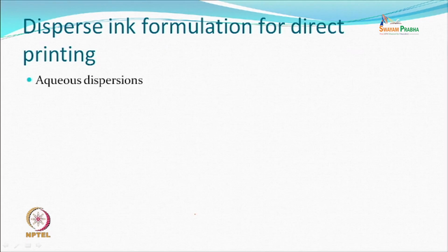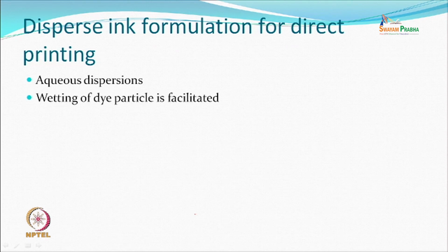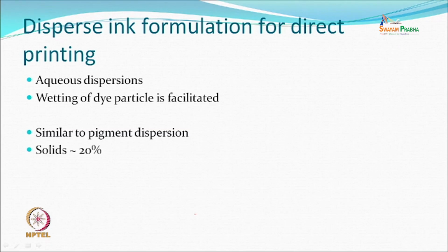So these formulations are obviously aqueous, which means a dispersion. Wetting of the dye particle is facilitated so that the particle remains wetted, satisfied, and doesn't want to go anywhere else. Similar to the pigment dispersion process, approximately 20% of solids and the rest everything else. So that is how we look at it. You can have more solids also, but more solids means more other agents to stabilize. That will mean the viscosity can also increase, so you have to control the viscosity and not let it go very high.